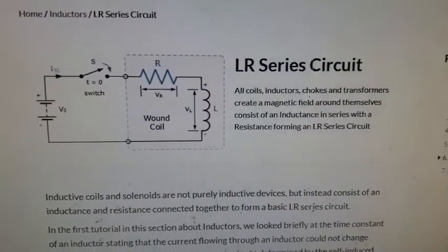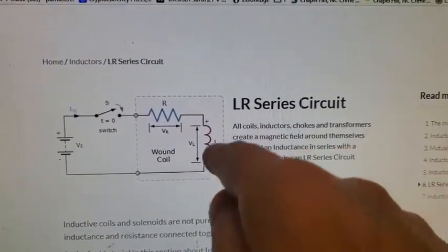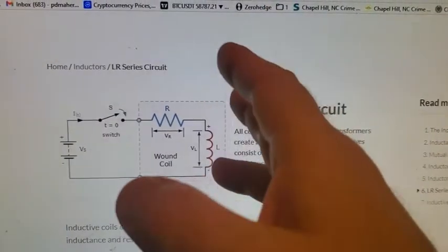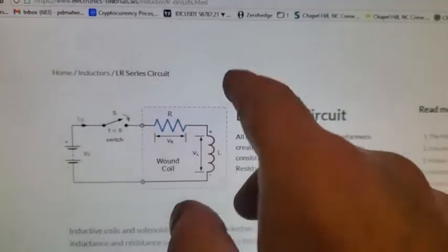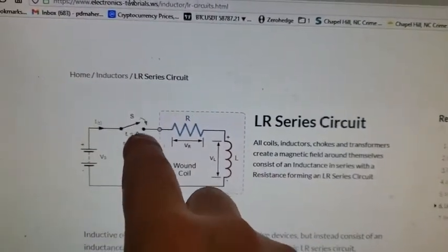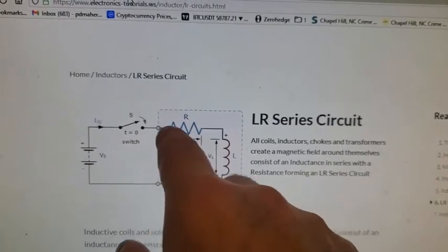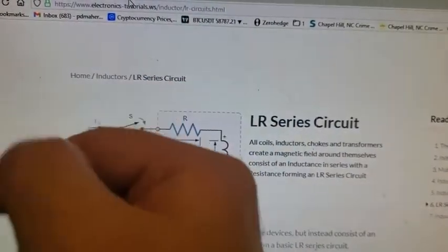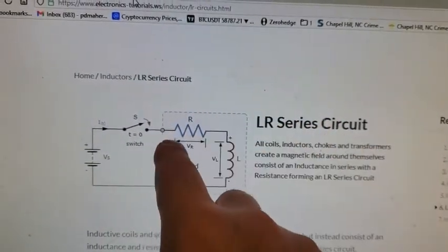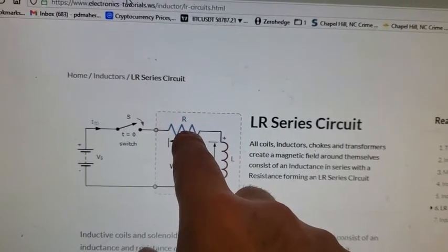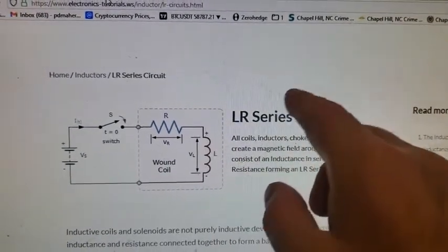resistance. If it were not present and there was only the straight line DC resistance and no inductance, now of course there'll never be a situation of no inductance that I can think of, but in idealized terms, if there were no inductance, as soon as that switch is flipped, then the current is established, I would guess at the speed of light, equivalent to Ohm's law, V equals IR, and the amp flow will be constant, and so it would be a perfect square. Because of the dynamic resistance, it's not perfect.